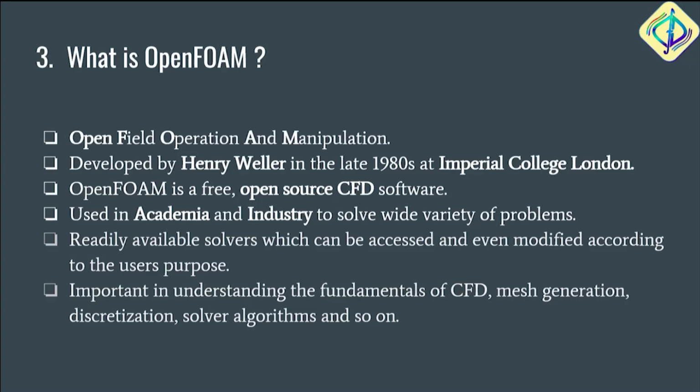But in OpenFOAM, you do have that privilege. You can modify the solvers based on your application. So suppose I have a heat transfer case and I want to introduce, say, another factor into it. I can open the backend code, modify that, and create my own solver. So those privileges are there in OpenFOAM. And also, if you're starting off with CFD and you want to learn the physics behind CFD, not just clicking buttons.